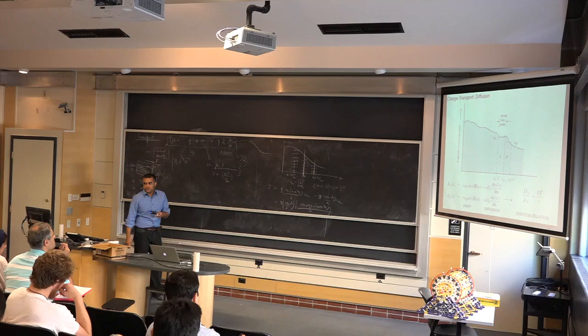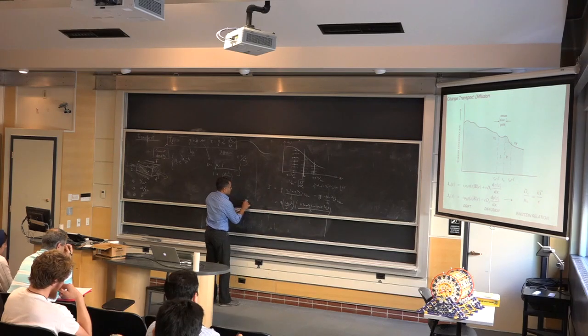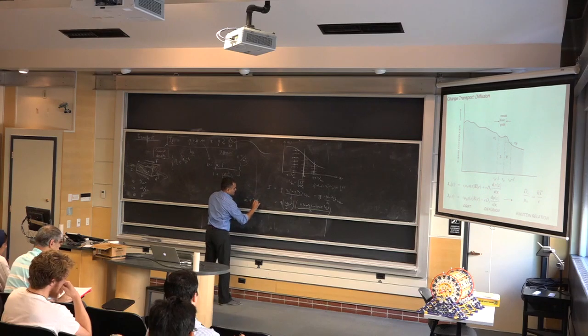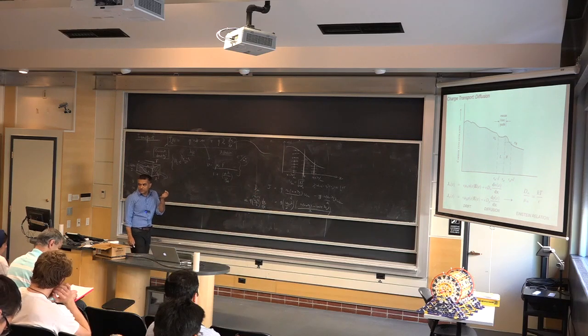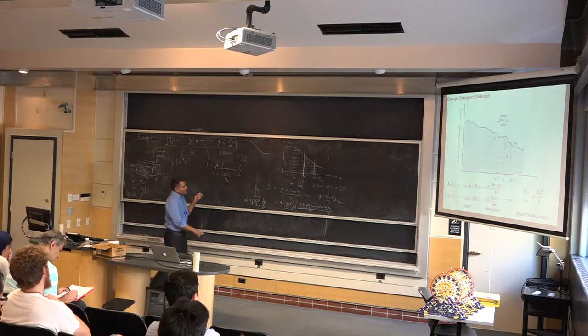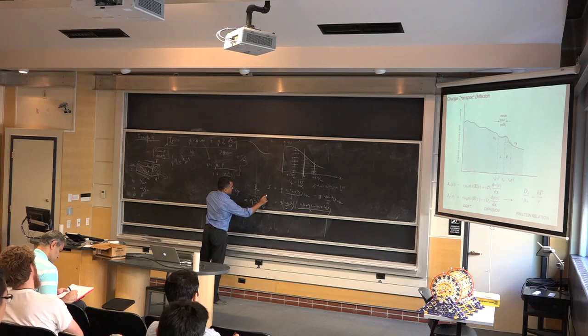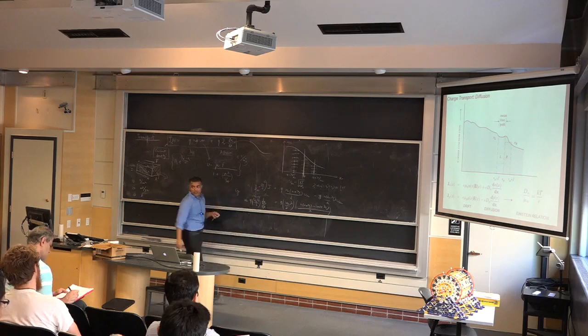And you realize that what this really is is the derivative. This is the definition of a derivative, dn by dx, in the limit of a very small lambda. As a result, what we get is q times this combined unit, the thermal velocity times the mean free path over 2, times dn over dx, and this is the heart of the diffusion coefficient. This is the definition of the diffusion coefficient. The velocity is in centimeters per second and the mean free path is in centimeters, so the diffusion coefficient has units of centimeters squared per second, which is a strange unit, but that's what it is.